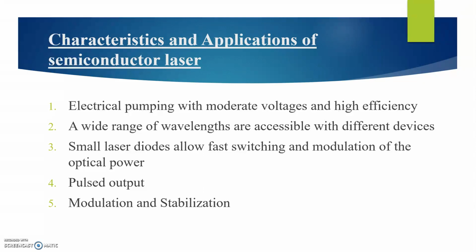Next important application is modulation and stabilization. A particular advantage of the short upper state lifetime is the capability of semiconductor lasers to be modulated with very high frequencies, which can be tens of gigahertz. This is exploited mainly in optical data transmission, but also in spectroscopy for stabilization of lasers to reference cavities, etc.